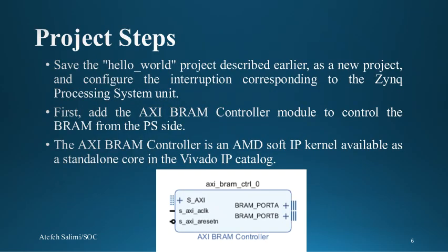From this slide on, I will talk about different steps that you have to do in order to complete the whole project. First of all, you should use the base project, which is Hello World, and then save it as a new project. This hello project, if you are new to the SoC design, I should re-explain it again in short. And it only contains a PS Zynq block.